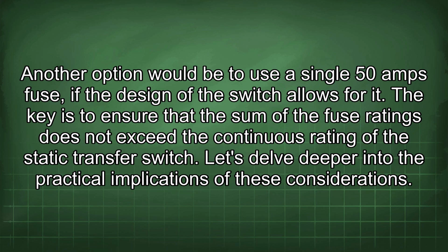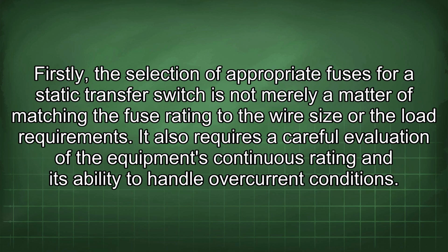Let's delve deeper into the practical implications of these considerations. Firstly, the selection of appropriate fuses for a static transfer switch is not merely a matter of matching the fuse rating to the wire size or the load requirements. It also requires a careful evaluation of the equipment's continuous rating and its ability to handle overcurrent conditions.